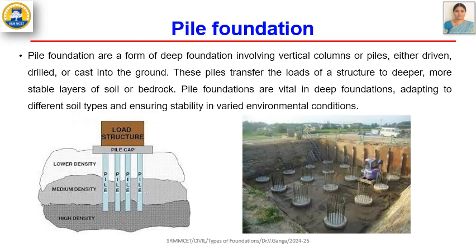Pile foundations are a type of deep foundation that uses long columns to support the structures. These columns are drilled into the ground. Pile foundations are used when the top of the soil is not strong enough to support the structure. Generally, to transfer the load from the weak soil to the stronger soil, pile foundations are used. Piles are either drilled or cast into the ground.